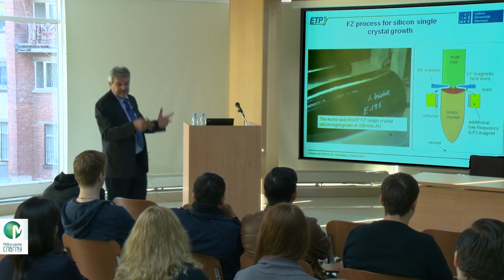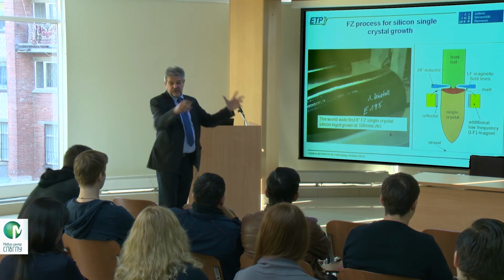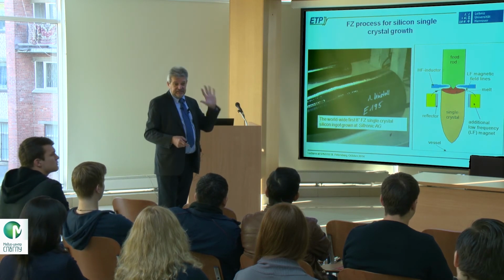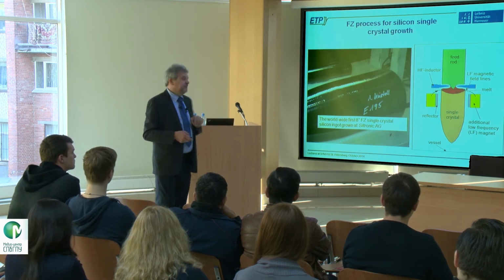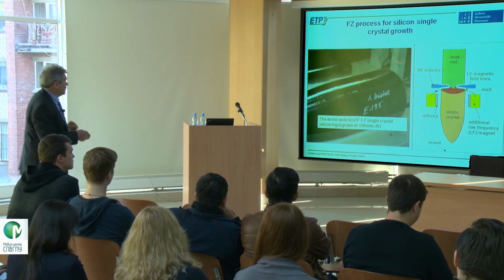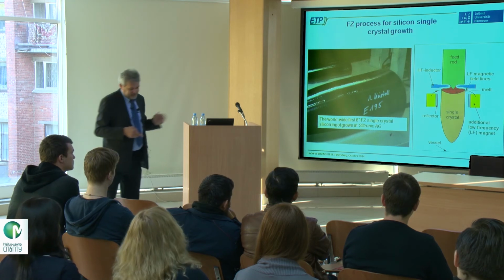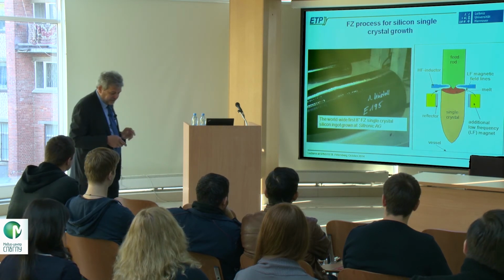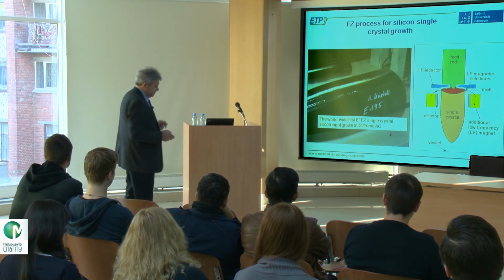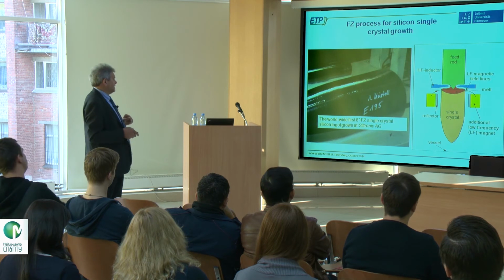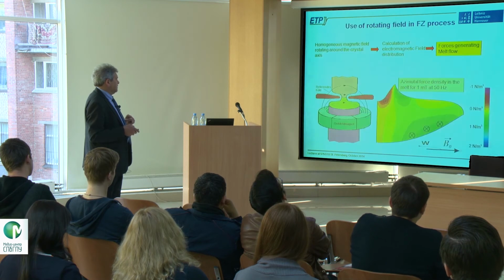And if you have one defect inside the wafer, you cannot use it. If you have microelectronics, you have 1,000 circuits on one wafer, and if one is bad, nobody cares about it. So you'd use the 999. Okay, so that means floating zone gives a much higher quality than Czochralski, and is therefore used for power electronics, but it's more expensive, of course. I think only 10% are made by floating zone, 90% is made by Czochralski, because it's cheaper and simpler.